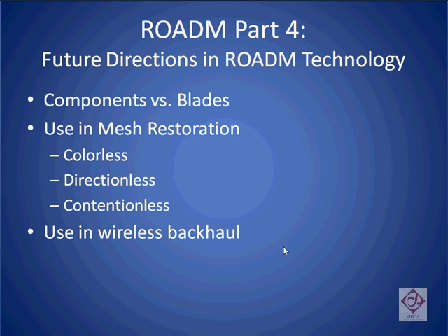And finally, although we have spent much time discussing how ROADMs might get more complex in the future, they may also go in the other direction as well. Smaller port count ROADMs might get installed in the wireless backhaul network. While we've typically talked about ROADMs being used to extract frequencies of light, they can also perform the opposite function by taking fibers that are lightly loaded and adding frequencies to them to make them more heavily loaded so that costs of transport can be reduced.